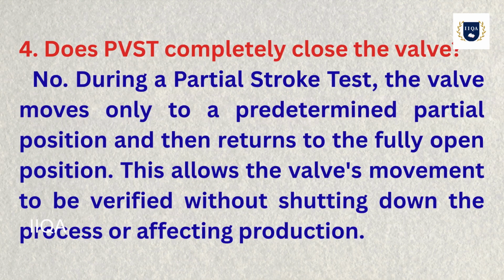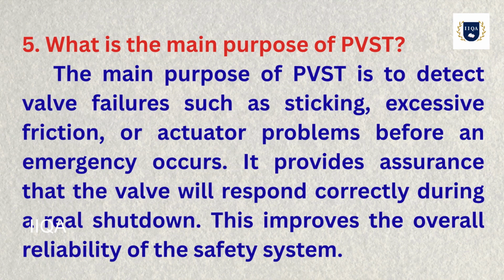4. Does PVST completely close the valve? No. During a partial stroke test, the valve moves only to a predetermined partial position and then returns to the fully open position. This allows the valve's movement to be verified without shutting down the process or affecting production.